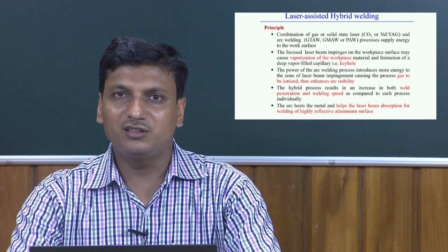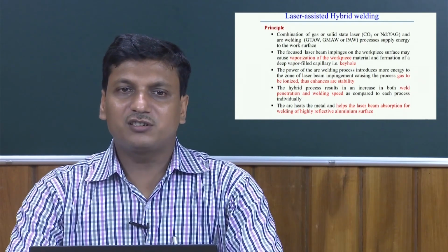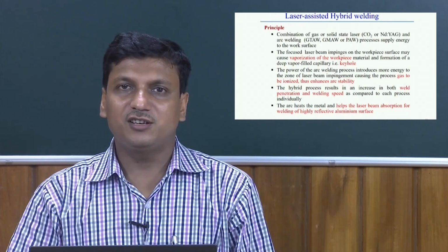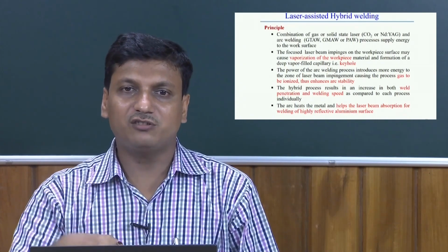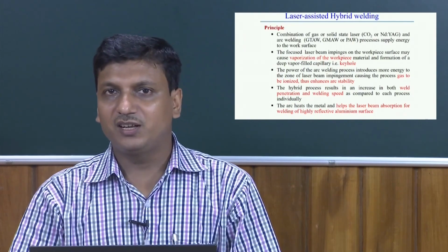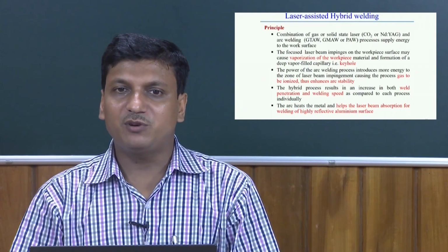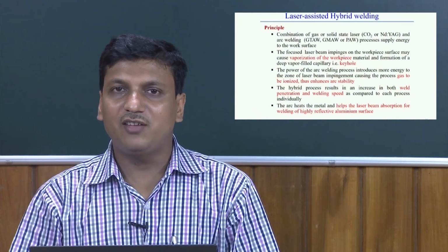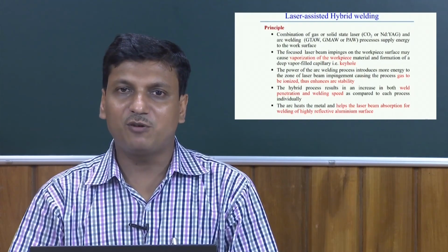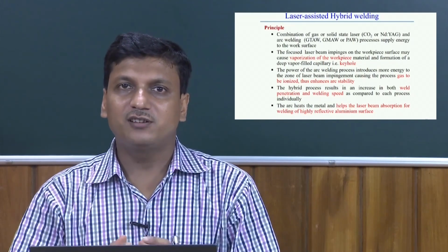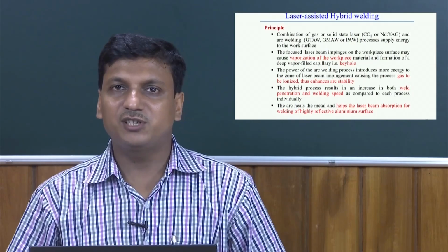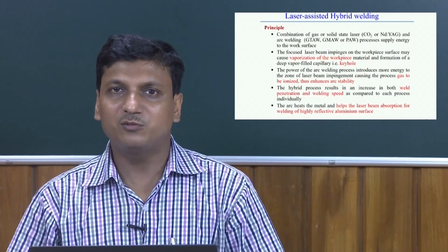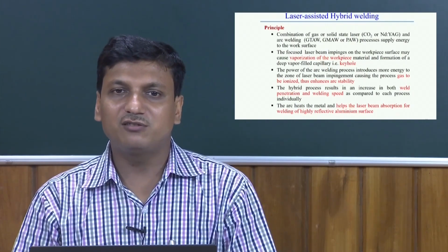First, the focused laser beam impinges on the workpiece surface, and that may cause vaporization of the workpiece material, and the material finally forms a vapor filled keyhole. That means the keyhole mode is mostly used in hybrid laser welding process.